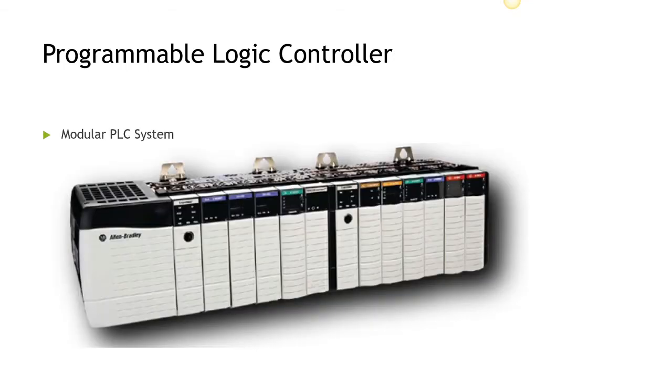This is a modulated PLC. This is what you'll have in the second year. This is also an offering by Allen Bradley. This one, each specific card that you place in here has a specific function. So the very first card to the left is the central processing unit, and that's all that it does. You cannot wire any inputs or outputs to it. You have to add a second component, another card, that is either an input card or an output card.